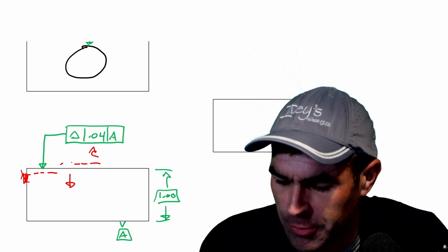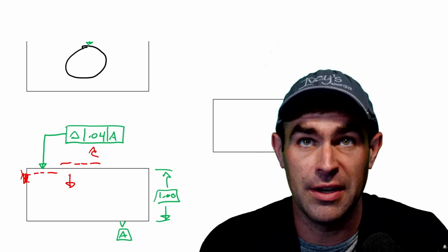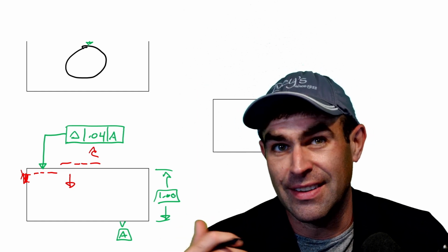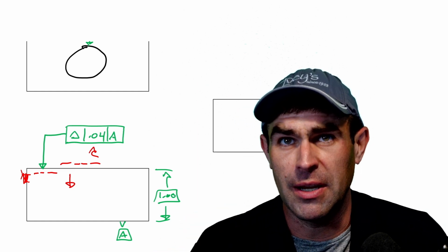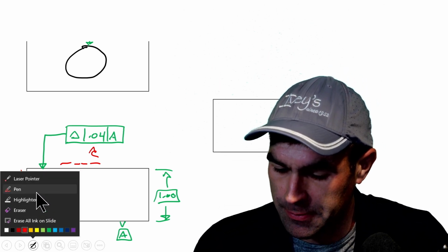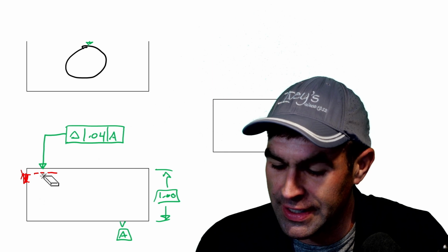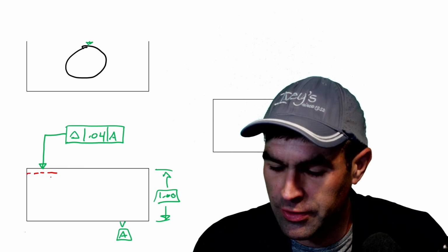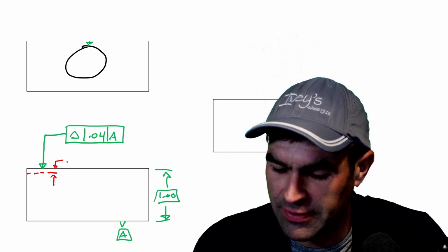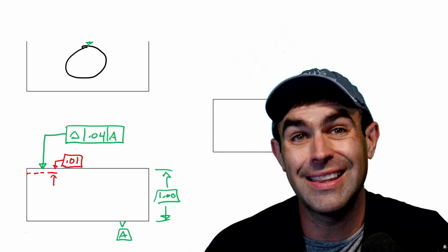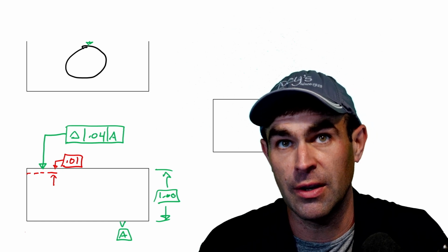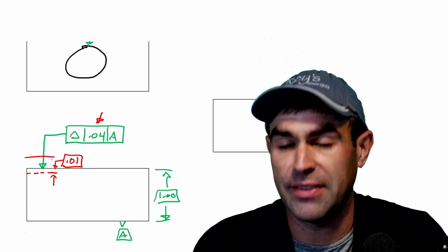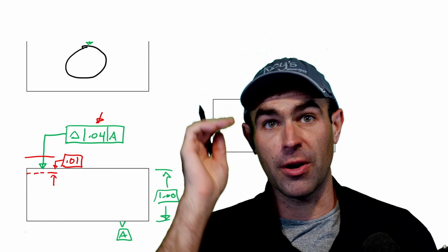I could put this phantom line on the outside, right, and point to it, and it means it applies the other direction. The phantom line itself is just a set distance, right? It is not scaled, is what I mean. If for whatever reason you needed an unequal profile, what you do is put a basic dimension on the phantom line, right? You only need one basic dimension. So in this case, 10 thousandths of this 40 thousandths is inside of the part. The rest of the tolerance zone is on the outside of the part.